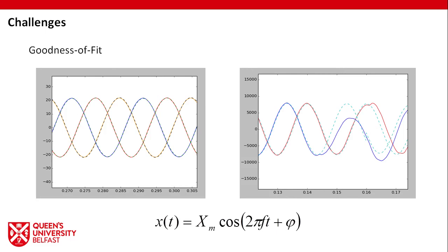The phasor measurement unit has tried to produce a synchrophasor which expresses what is being observed, but it doesn't have the language available to it to describe what is going on. It can't describe a DC bias. It can't describe this unusual distortion in the waveform. So it is providing its best guess at a synchrophasor that roughly fits those. And we can see from the dashed lines that it's not a very good fit.